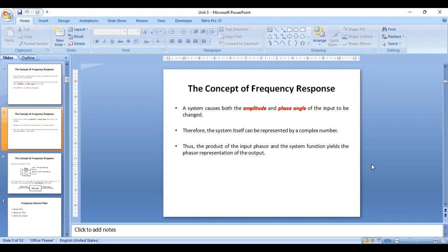There are some advantages of frequency response analysis, which include: the absolute and relative stability of the closed loop system can be estimated from the knowledge of their open loop frequency response. The practical testing of the system can be easily carried out with available sinusoidal signal generators and precise measurement equipment. The effects of noise, disturbance and parameter variation are relatively easy to visualize and to incorporate corrective measures for.